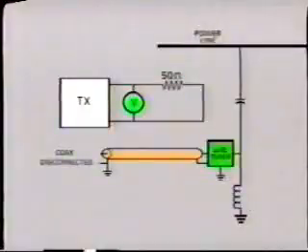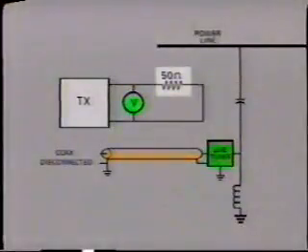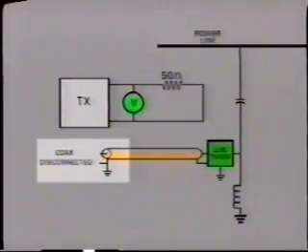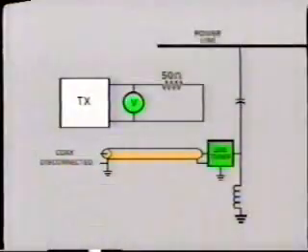Of course, here we're presenting just a general outline of tests to be performed. In practice, you'll have many more fine adjustments to take care of. Make sure that you follow each step laid down in your specific equipment instruction manual. And don't forget to remove the dummy load and reconnect the coaxial when the tests are completed.